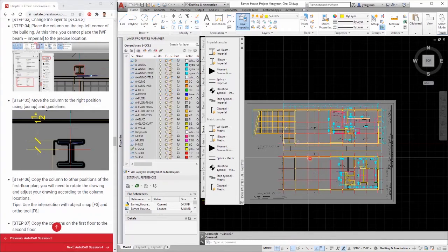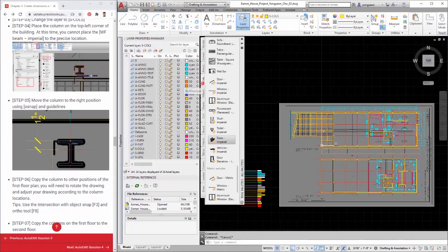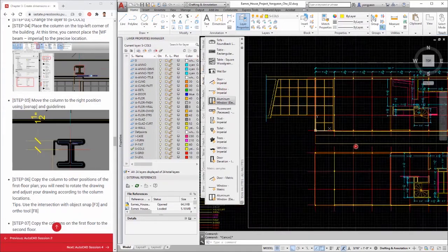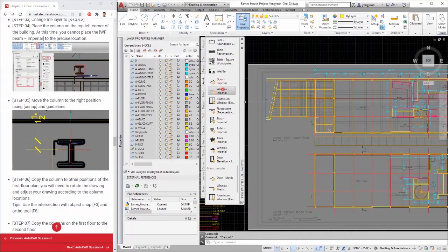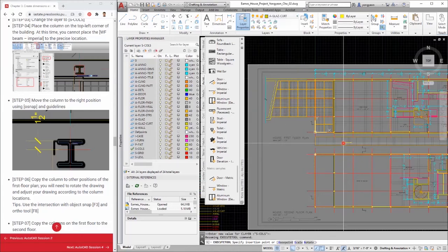You can find Door Imperial and Window Imperial from the Architecture tab on the Tool palettes to add to your drawing. However, the currently loaded blocks on the tool palettes are called Dynamic Block. A dynamic block is a parametric block that users can easily modify. Step 1. Click Window, Imperial on the tool palette. Step 2. Place Window, Imperial block in your drawing.